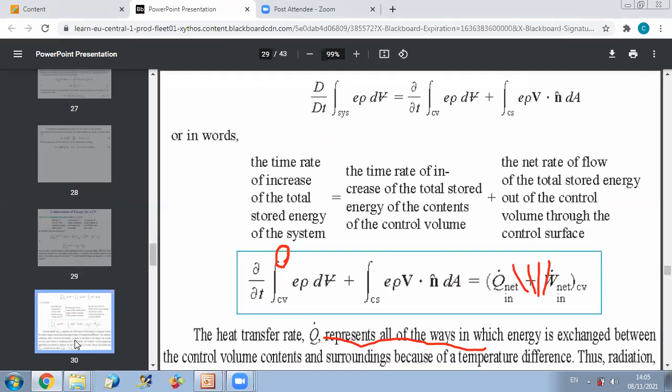Okay, so you will have, let's say, a turbine or a pump. You should know that for the pump, I should supply work, so I should do plus W dot because I'm supplying work. While for a turbine, it's producing work, so it's minus W dot. Okay, so that's it.